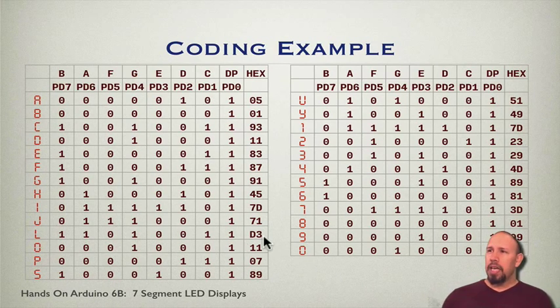The other thing is, since this was originally designed for numeric displays, and since we can readily do all the digits using the 7-segment display, that was enough. If you actually want to do alphanumerics, then it's more common to use what is called a 14-segment display. The 14-segment display not only has the ones around the sides, but it has things in the middle that allow you to do X's and so forth. With this 14-segment display, you can do full alphanumerics in a more naturally readable form.